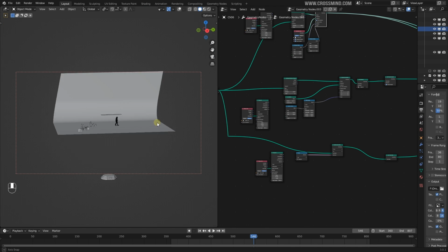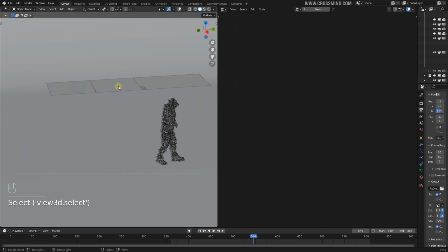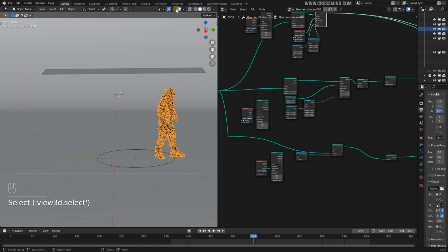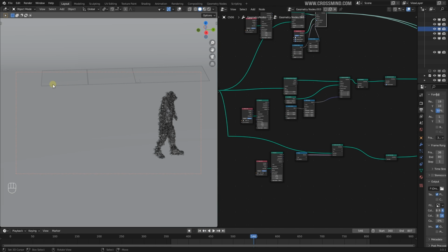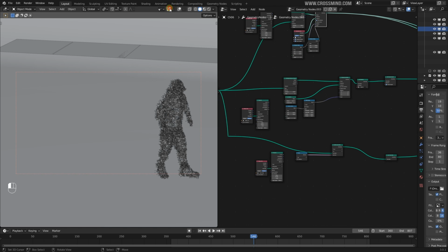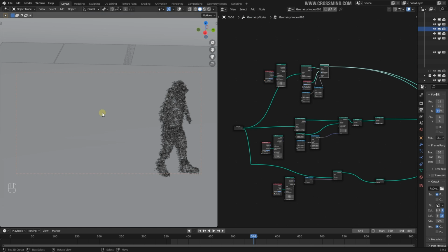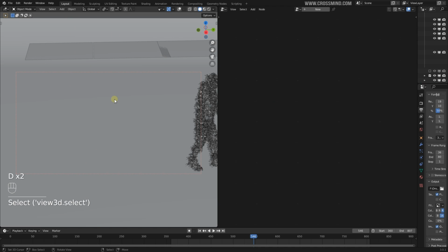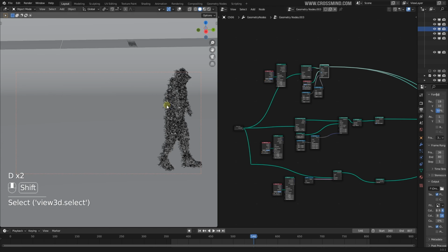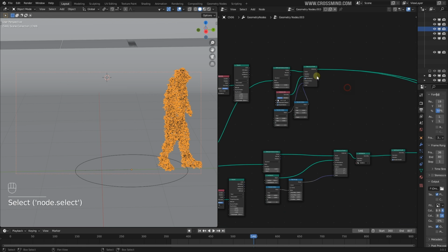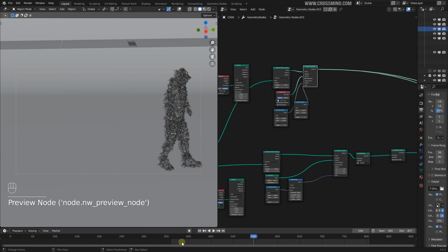Now for the last sequence, what I have here is there are 3 planes, 1, 2 and 3. So what I wanted was basically whenever this character slides under, passes through these different planes, the density and the effect changes on the character. So basically what I did was I'm using these 3 planes to cast rays vertically down in the -z direction and control the density, sorry, the selection based on that. So for the first setup, I have this grass kind of a thing.